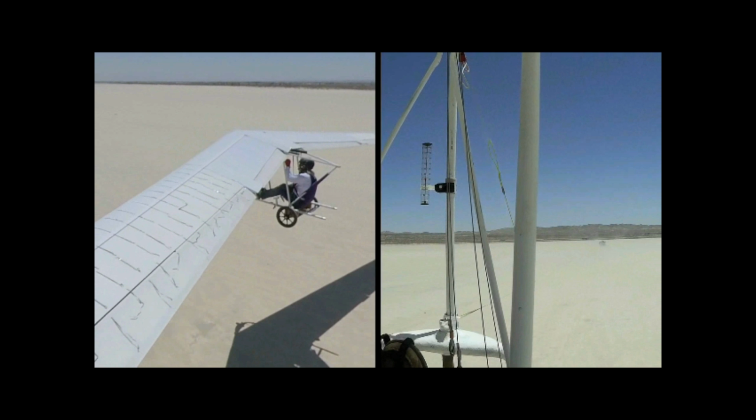As soon as the release occurred, that nose-up pitching moment went away instantly, and the nose is going to drop on me because I don't have that nose-up pitching moment. So I rapidly feed in some up elevator, and that'll bring that elevon back up into a neutral position, and you'll see all the flow reattach. Happens in a matter of just...